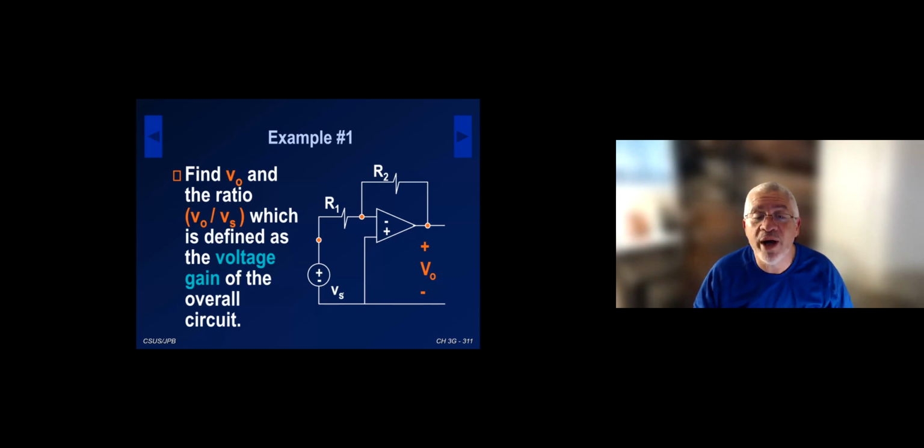So remember, before I start solving anything here, again, I'm going to choose a reference node. And then what are we going to do here? We're going to say, okay, no KCL here. We put an X, no KCL at the output of an op-amp. That doesn't mean no current, by the way. Obviously, the op-amp puts out current. All right. No KCL here because in the model, we have a dependent voltage source at the output.